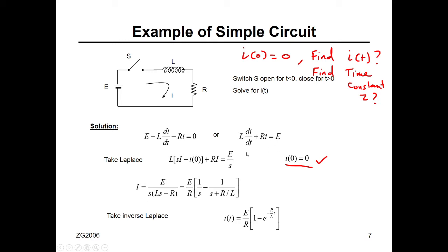Now this is similar to any differential equation you learned how to solve in chapter 2. Take the Laplace transform, solve for I of S. How you go from this step to this step, Shabab, let me remind you: partial fraction expansion. You know this from chapter 2. Then you go to the table, find the inverse Laplace. This one will be a step function. This one will be exponential e to the power minus R over L t. So this is your solution.